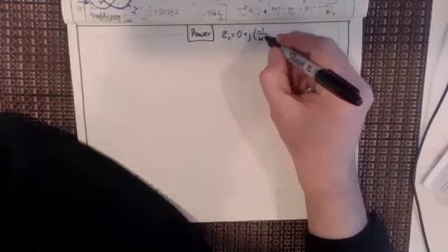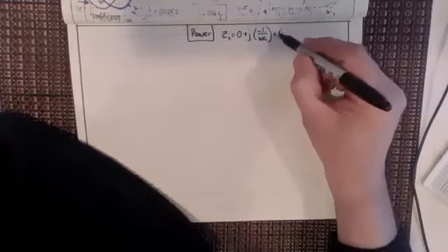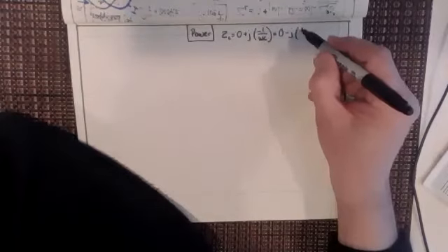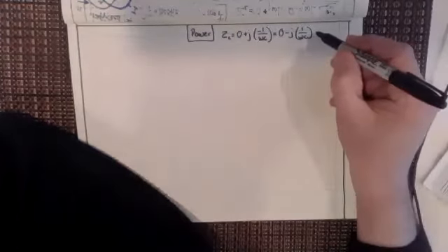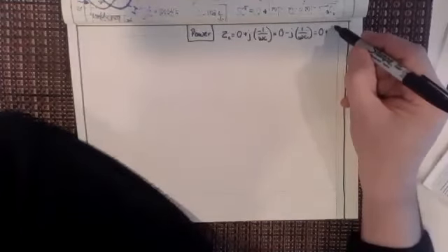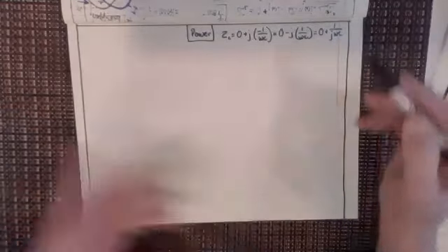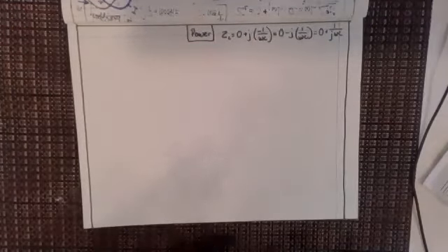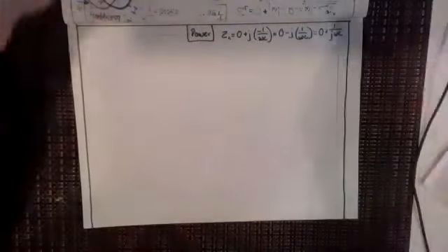I'm going to write it in a couple ways right here. So that's how it's written, or it's written as 0 minus J 1 over omega C, which of course would be the same thing if you think about it. And then some people write it as 0 plus 1 over J omega C, which is the worst way to teach capacitive reactance, just an impedance. It's just the worst way to teach it because it throws everything all out of whack.